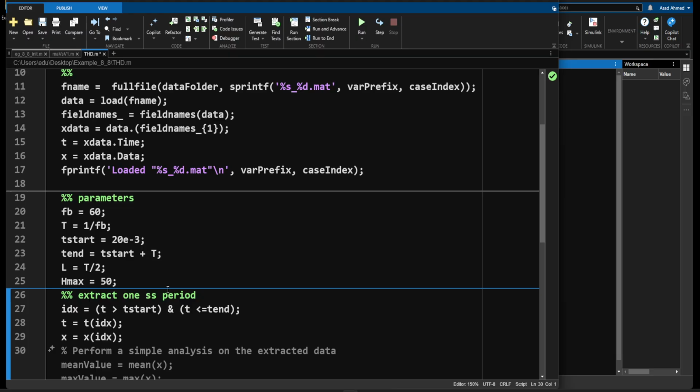Now in the signal itself, be it voltage or current, there is also a DC part if we do the analysis. So for the frequency spectrum, we want to leave that DC part since we're interested in the AC signal analysis. To do that, we need to subtract the mean value or the average value of x from x itself. So the DC part is now removed.